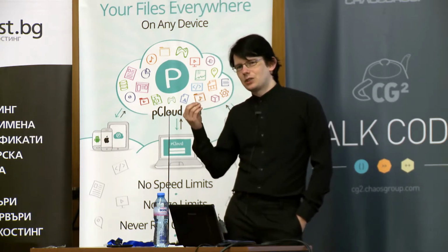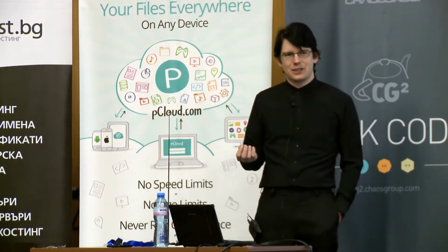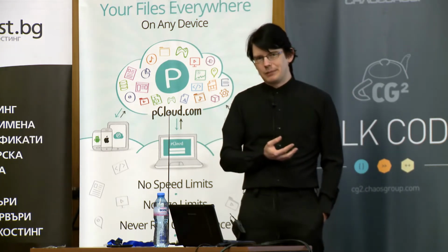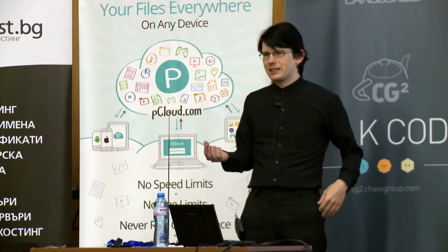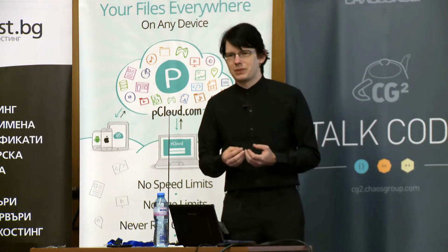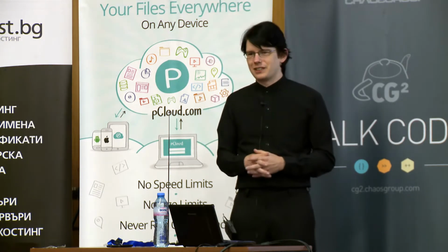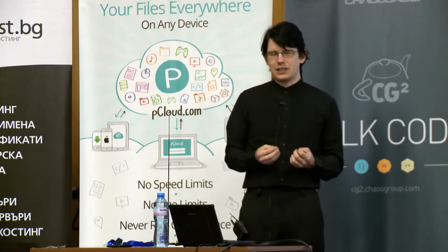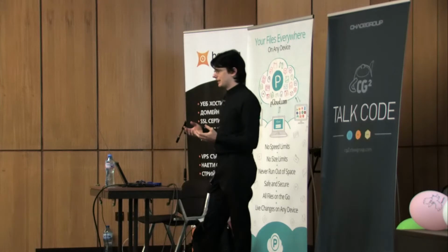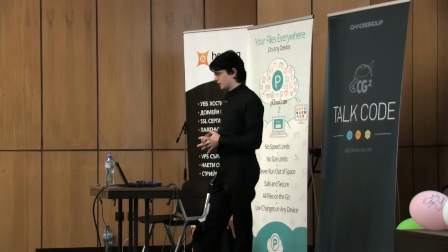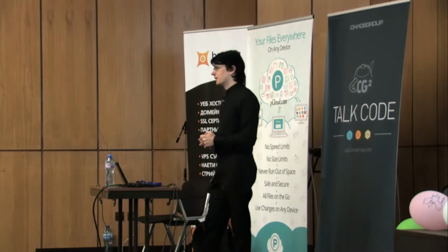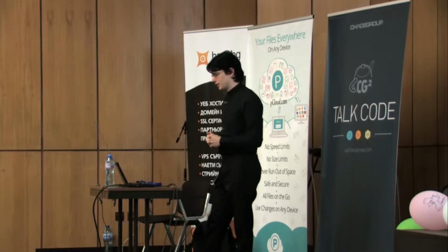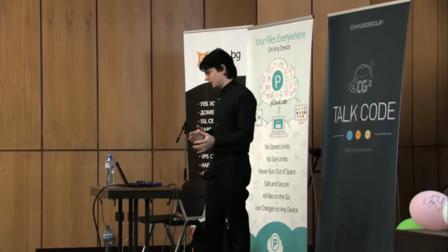the information how to program that radio and the tools and the specification and so on, the manufacturer doesn't release. So basically, yes, you have this generic radio device, but the manufacturer ships it with a firmware that's specifically for Wi-Fi only or for something like that. And you don't have the information, or often also not the tools, to actually do anything else with those devices, because it's in some DSP ROM, or even hardwired logic inside the receivers. So they use SDR technology, but they have removed the flexibility from that. And that's sort of sad.